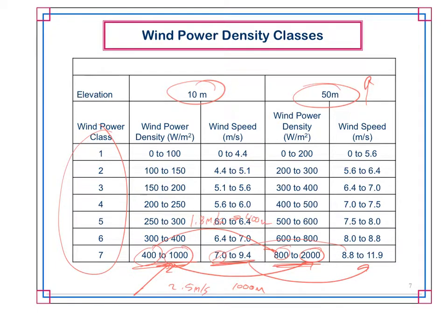We'll look at maximum theoretical efficiencies of about 60%, but in reality, most wind turbines are about 40 to 44, 45%. So that's why you've seen a lot more commercial wind, because up until recently, you had PV arrays getting 10% efficiency, really low. And wind turbines, without that much effort, can be at 44, 45%.